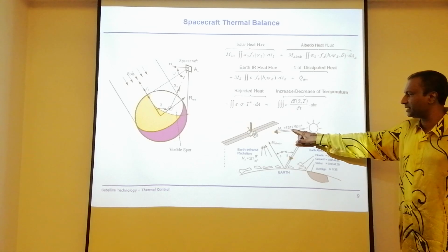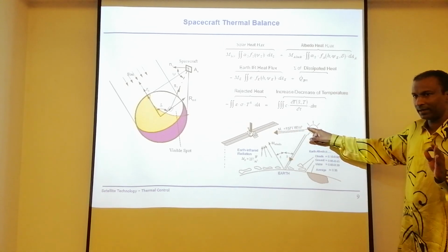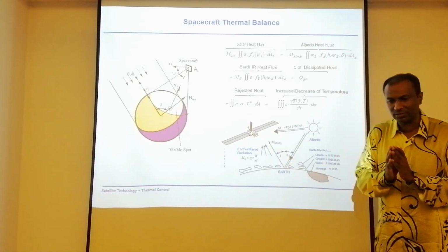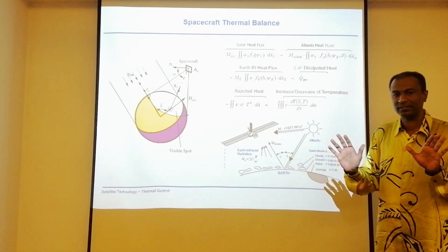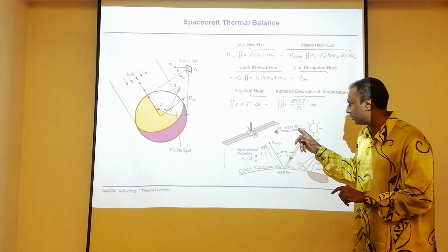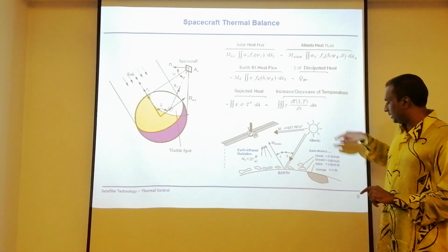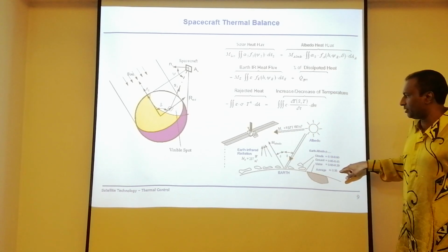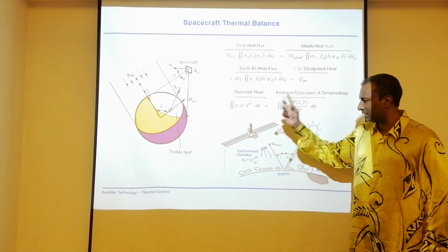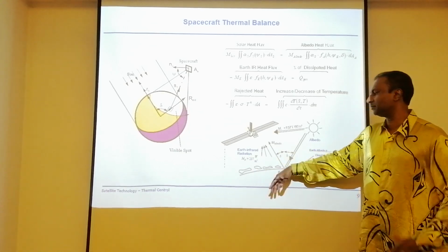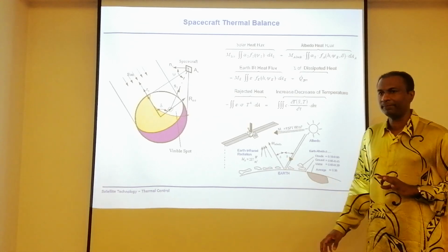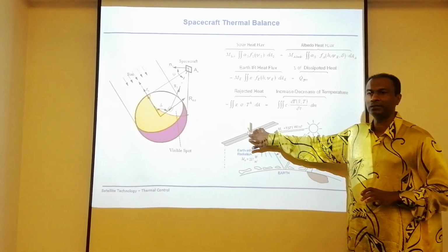0.35 of the actual sun ray which hits the spacecraft. So 1371 watt per meter square from the sun hits the spacecraft, and you need to know how much of the area is actually exposed to the sun. About 0.35 of it comes as albedo back to here. And another one is basically infrared. It's also given here. It's around 237 watt per meter square hitting our spacecraft.